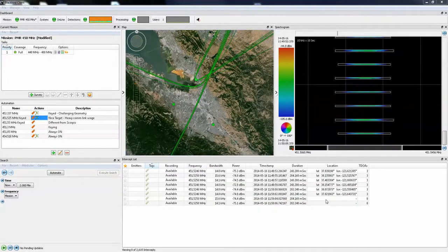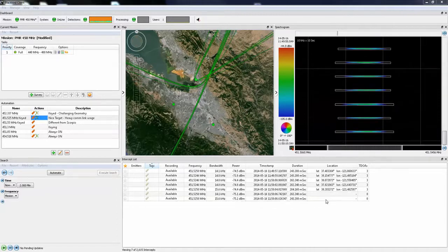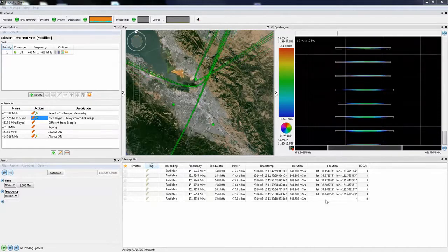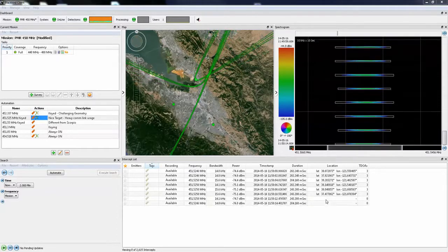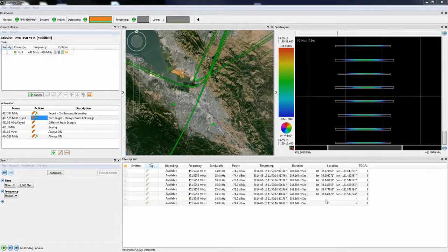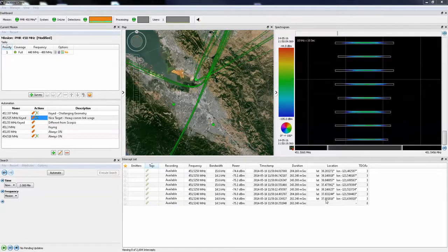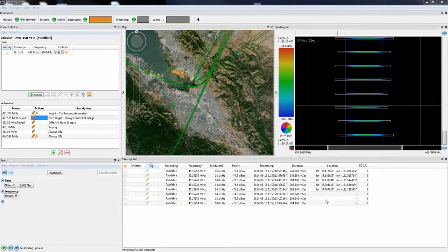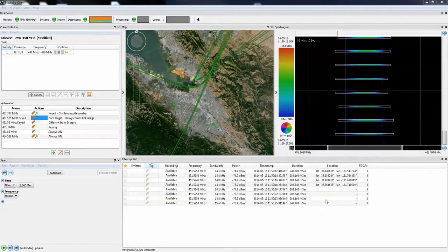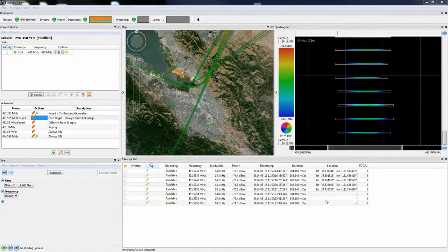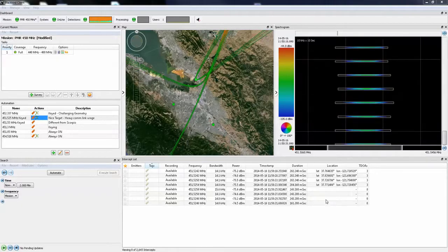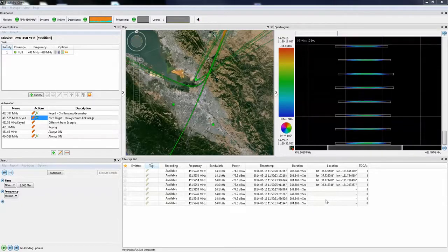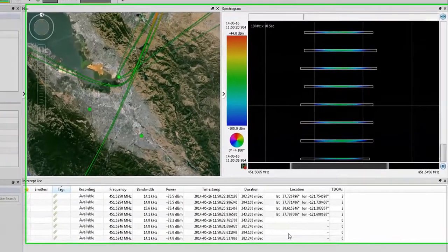In this movie example, we'll be looking at a modem that is sending 200 to 300 millisecond data bursts every 2 seconds with a bandwidth of around 15 kHz. As the system detects each burst, a lookback TDOA measurement request is sent to each TCI Model 350 system to request IQ data for that frequency and bandwidth and time period. The IQ data are then correlated, and the resulting TDOA isochrones and geolocations are shown in the map, with geolocation results appearing in the intercept list table.